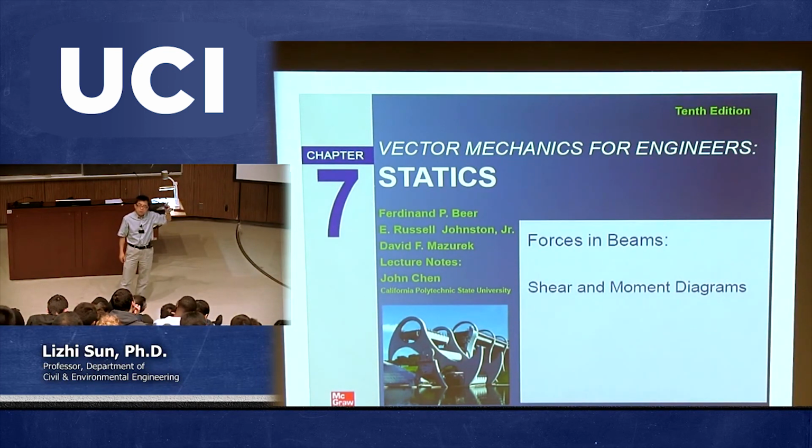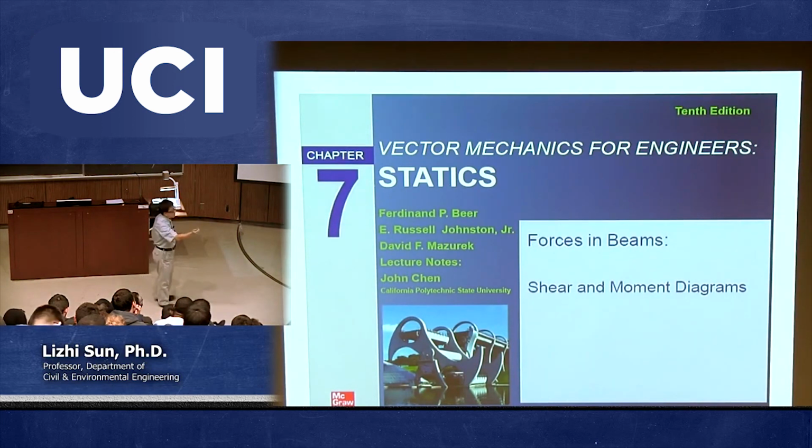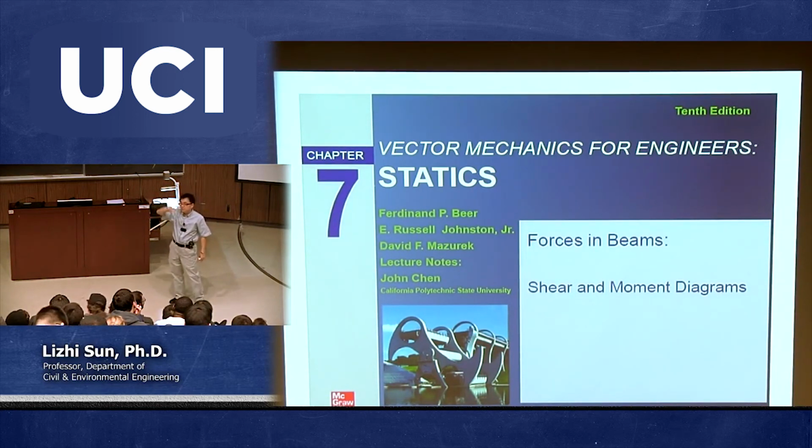So that's why you should not only plot. You should give me the procedures. Okay, step 1, to calculate the reactions, most likely, right? And then you're going to decide how many segments you need to cut. Okay, each segment, write down those equations. Okay, if you do not write those equations, for whatever reason, you just plot directly, and many times those are not straightforward. How I'm going to assume you know how you calculate it, right?